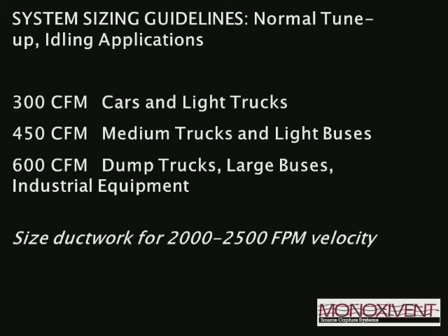Now, these are some very simple guidelines, and please note that these are for normal tune-up or idling type applications. There are many other applications like dynamometers and maybe heavy hydraulic testing or pump testing, but the criteria that I'm talking about today is for normal tune-up and idling type applications. So for cars and light trucks in an idling or tune-up type application, we recommend 300 CFM at 4 inches of static pressure. Next is medium trucks and light buses, 450 CFM at 5 inches.